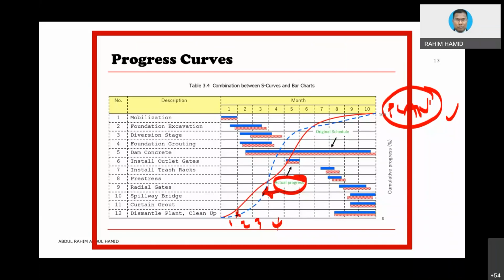So you must speed up the work, bring larger equipment, bring more people, work overtime, and work during the holiday to catch up. So it looks like, for instance, in week number 1 to 3, they already caught up with the original schedule, and then they are able to progress a little bit faster than that. Okay, that should be fine. So in the real situation, the graph could be up and down, it doesn't matter. The most important thing is this point. By hook or by crook, the concept of finishing the project within the time should be the one that we follow.